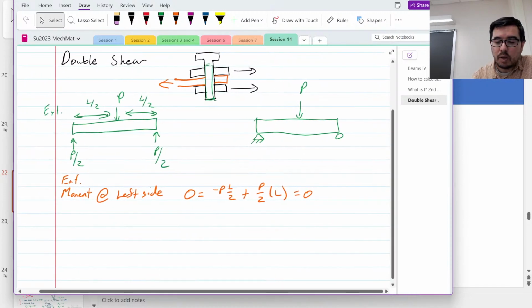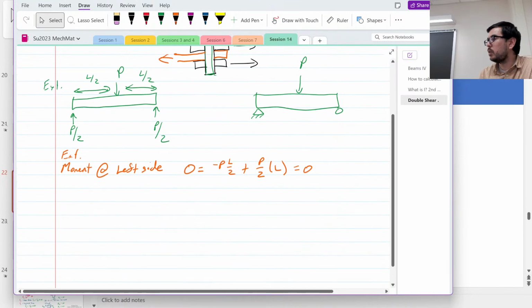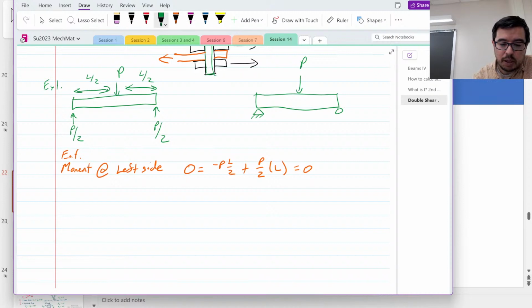Now, how do we go about figuring out what the internal shear force is? Well, we can just use the cover-up method. We draw the beam, and we use the convention. Okay, the convention is that V is down when we expose the right, and M is like that.